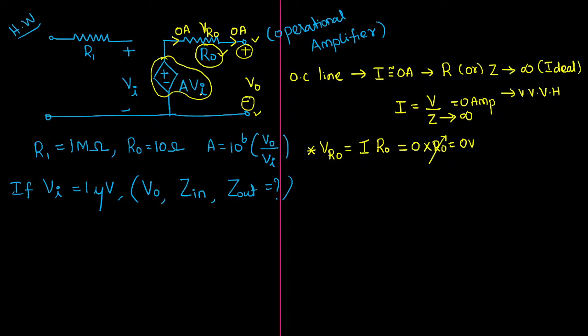First of all, I just wanted to know whether it is a voltage source or not. First of all, that is a dependent source. Yes, sir. You must agree with me. Why? What is the representation of a dependent source? If a source is represented with the help of a rhombus symbol, some people call it a diamond. If it is represented in a diamond symbol, then this source is considered a dependent source. A dependent source usually will be controlled by someone.